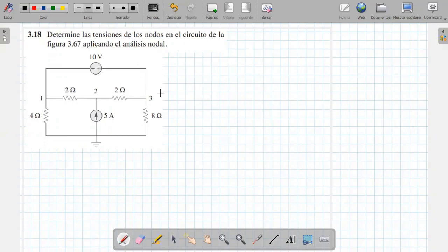Well, the first thing I always recommend is to identify the flow of currents in a circuit. Do a visual analysis, and based on that direction of the currents we can apply node analysis. For example, I'm going to start at this 5 amp current source, which makes it easier for me to determine the direction from here. Everyone can do it however they like, but I am going to start here for the following reason.